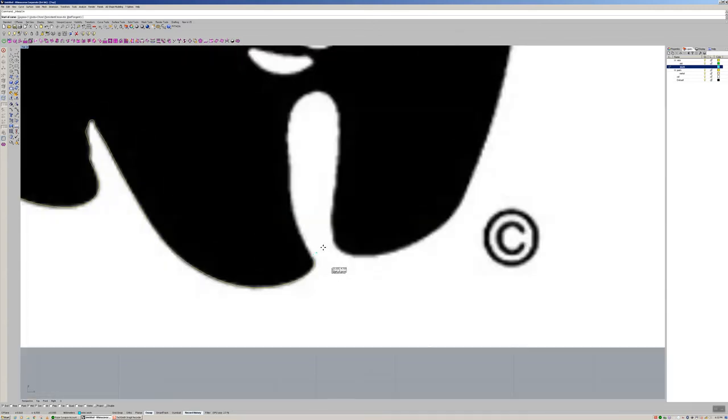And down here, this is where it says end, near, point. So I'm going to turn off near, and I'm just going to keep it at end. So we're going to snap to the end. This is a very important thing I want you to pay attention to. So what I did was I got to a certain part that I could probably wiggle, but sometimes it's good to just end the command by right-clicking. So you right-click to end the command and restart the curve command and start it again from that point. That's how you connect it.